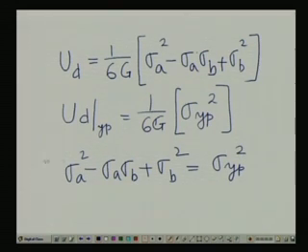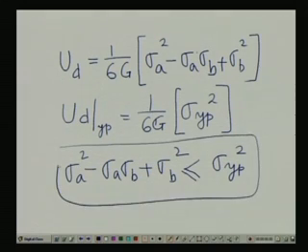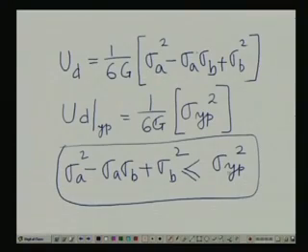Now, in this case, if we are going to have a safe stress design, then one can consider that the distortion energy is this one, and the limiting value we can write like this. This is the mathematical representation of the distortion energy theory. So, the distortion energy at a point is less than this yield point criterion.